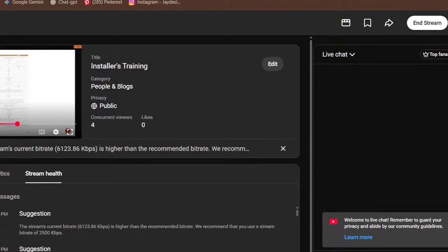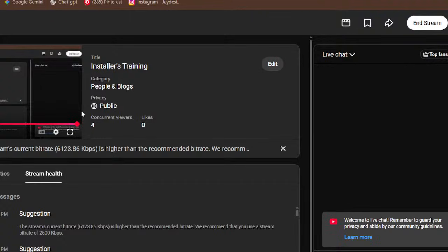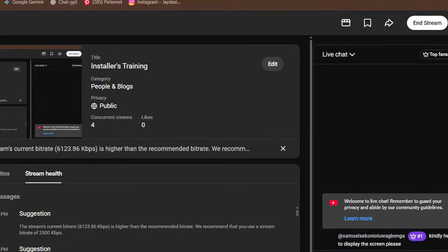So I told him he wants to parallel the smart load as well. I told him, no, you have to put the loads there separately. You don't parallel the smart load. We parallel only the main, with different breakers.